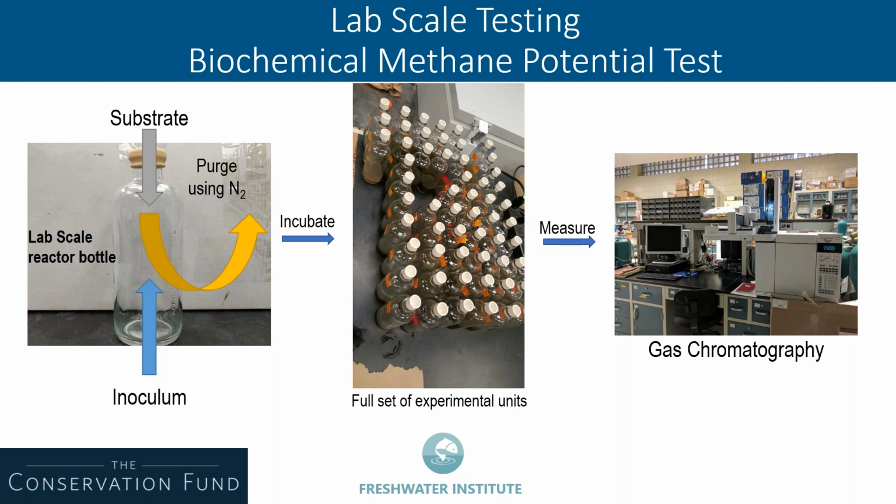Through this methane potential test, we can also estimate the biogas and methane production of a mixture of wastes. For example, the offal that is generated on a fish during fish harvest, we can add that fish offal into the mix. Fish offal also contains carbon, so in theory, it should help enhance the methane production, which leads us into what we call co-digestion.